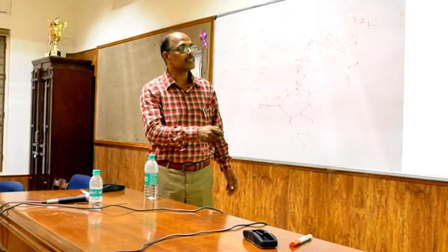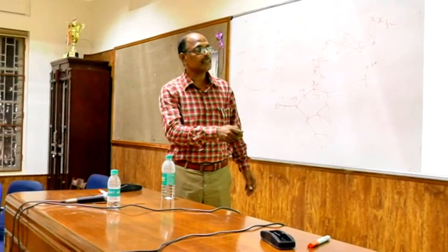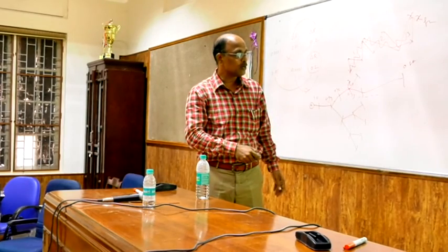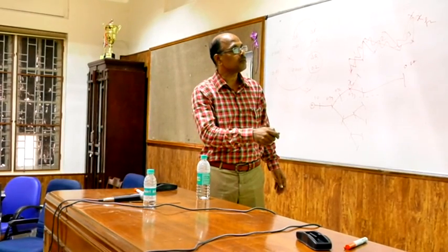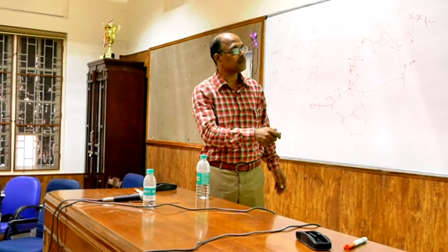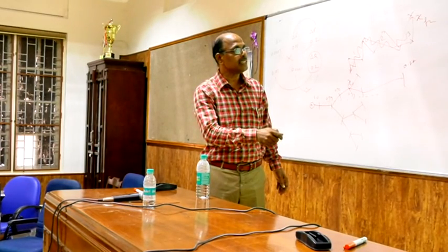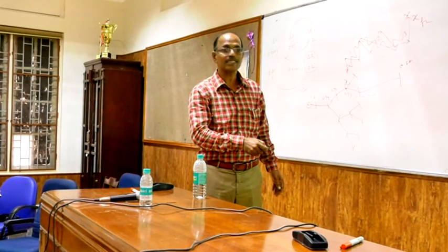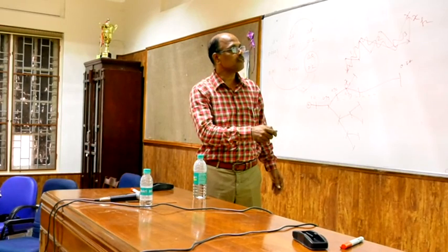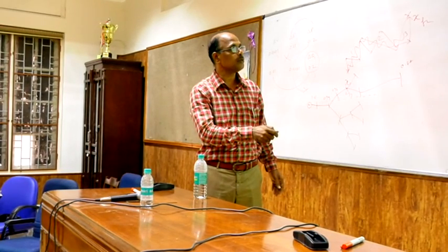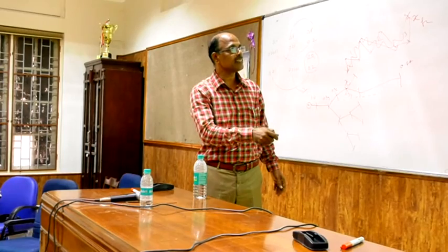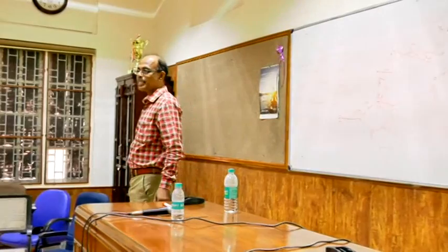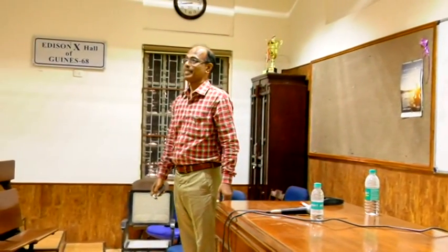The feeder current 6 is the current at node 6. So the 6th branch is nothing but J6, the 7th branch is nothing but J7. What about this 5th one? The 5th feeder is equal to J5, J6, J7. So I5 is equal to J5 plus J6 plus J7. Similarly, feeder 4 is equal to J4, J5, J6, J7. In this way, we can write the expression for all branch currents.